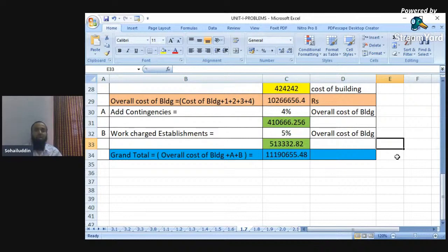So in this way, we have seen the problems related to the plinth area. This type of problem has been asked. In the starting lectures we saw simple multiplication problems. But in university exams, this type of problem will be asked, in which we first have to find the area covered by corridors, veranda, walls and columns, and the addition will be the plinth area.